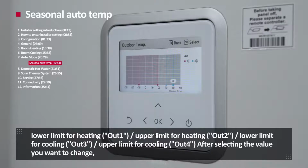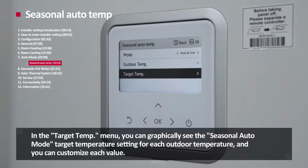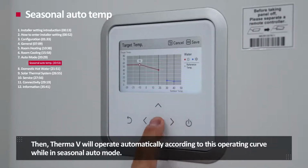After selecting the value you want to change, you can increase or decrease the value with the arrow buttons. In the target temperature menu, you can graphically see the seasonal auto mode target temperature setting for each outdoor temperature, and you can customize each value. Then, Therma V will operate automatically according to this operation curve while in seasonal auto mode.